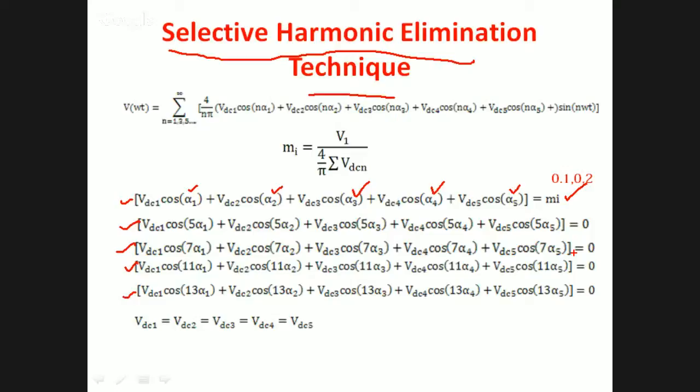Now these equations, how will I solve them? It is not an easy method to solve this. These are transcendental equations, and they are a little tough to solve. These transcendental equations I can solve using different numerical analysis methods. You have Newton-Raphson, you have Gauss-Seidel, all those methods you can use, or you can solve using optimization techniques. You can find the optimal angles at which the THD will be minimum. So how will you find the optimal angles alpha 1, alpha 2? You can use particle swarm optimization. You have already learned it, I think; sir would have come and taught you particle swarm optimization. So you can use GA, PSO, or any ant colony algorithm, anything, and solve these equations.